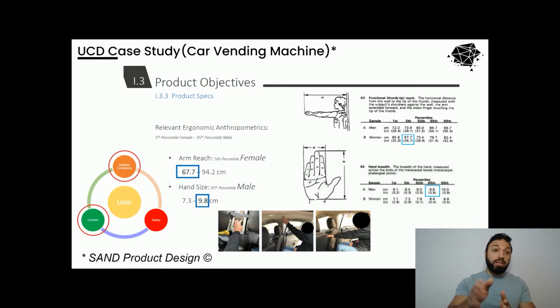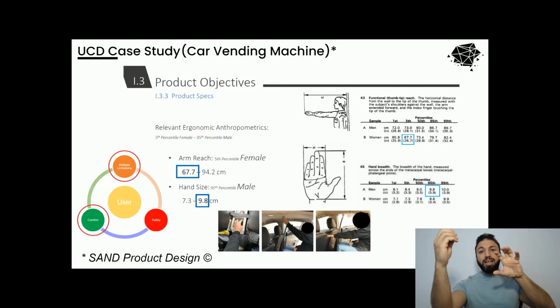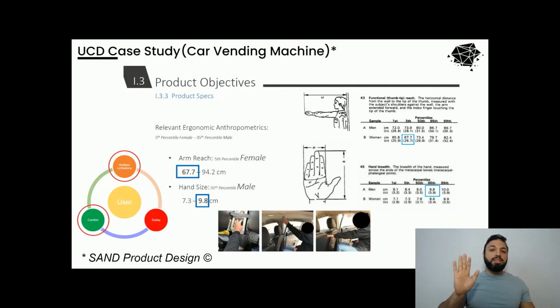At this point in time, we didn't know. This is why I'm saying if we wanted to have what we called the fixed compartment design, which is basically the compartment is like a small box where the snack is inside and just opens, so you reach in and you take the snack. There is another design which is more commonly used with the bigger machines, where basically you have the items displayed, then there's a robotic arm or a robotic spiral that pushes the goods and it vents through one common vent. We eventually did the compartment design, not the common vent design. But for that particular study, we considered both, because at this point in time, we didn't know which one we were going to really proceed with, right?